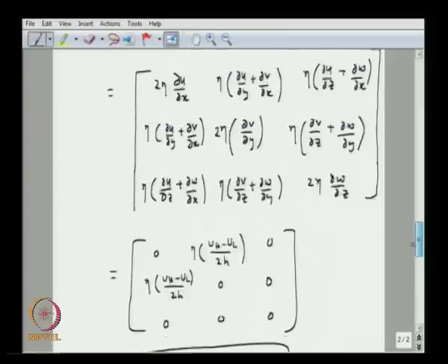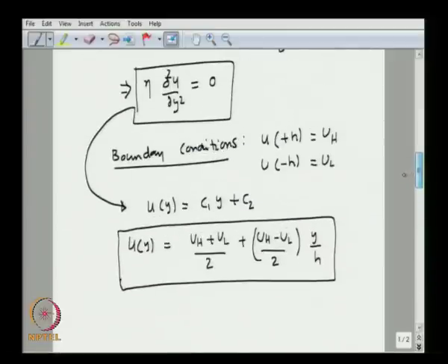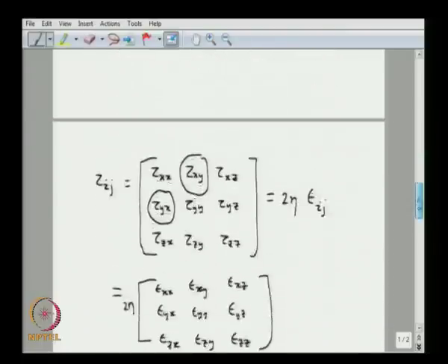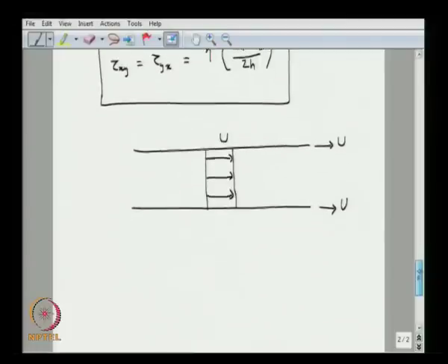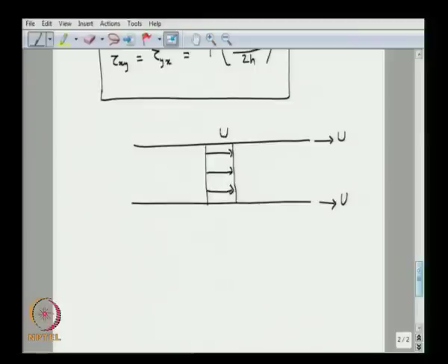If you go to this velocity profile equation, this term will drop off. So, this will be 2u over 2, so it will be u, right. So, the velocity will stay at u throughout. Okay. So, the shear stress is going to drop out.